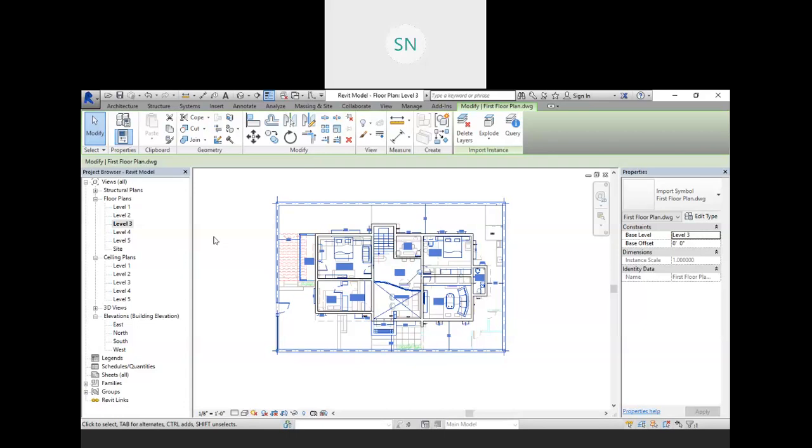Analytical level. Why are you using the structural analysis template, Sandeep? That template is for the Revit structure file. That's not our architectural template. If you are getting that analytical level over there, that is your Revit structure file, my friend. You are working in the wrong template. Choose your default template. See, over here we do not have the analytical template.